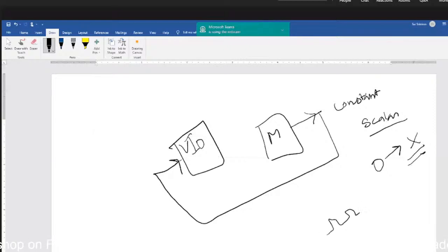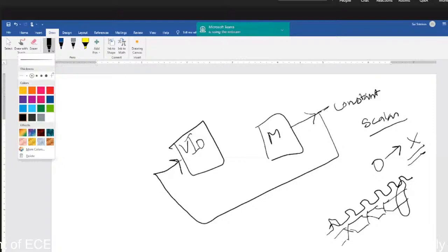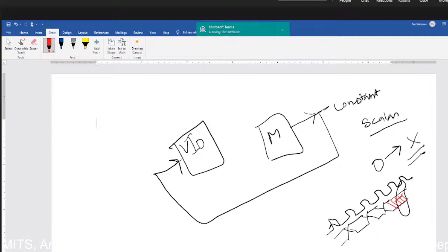But if the output is varying continuously with respect to time or a clock signal, then you cannot observe it in VIO. You will observe only the end value, but not the intermediate values. You will only be able to observe the end value when the simulation has ended, but the previous values you won't be able to observe in the VIO.